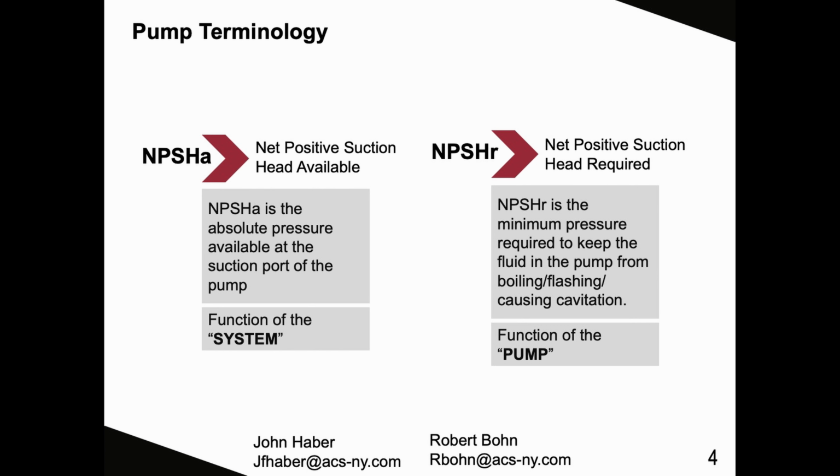One of the most important terminologies when designing a fuel oil system is the NPSHA, the net positive suction head available, which is a function of the system. So you as engineers have control over this regarding the valves, the fittings, the pressure drops through the system. Again, it's a function of the system.